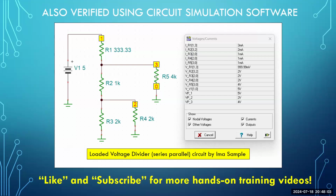The current through R5 was required to be 1 milliamp. Take a look at IR5. IR5 is also 1 milliamp. Take a look at the current that flows up through R3. That was 1 milliamp, and IR3 is 1 milliamp. Look at that. So at node C, don't these two currents combine? The 1 milliamp through R4 and the 1 milliamp through R3, don't they add to give us 2 milliamps going through R2? We measured it.